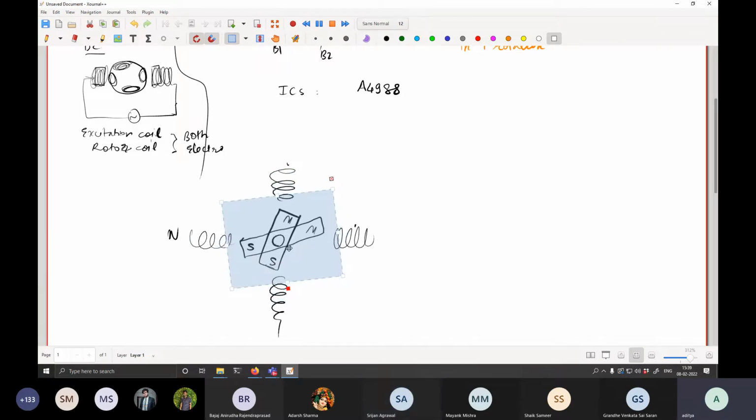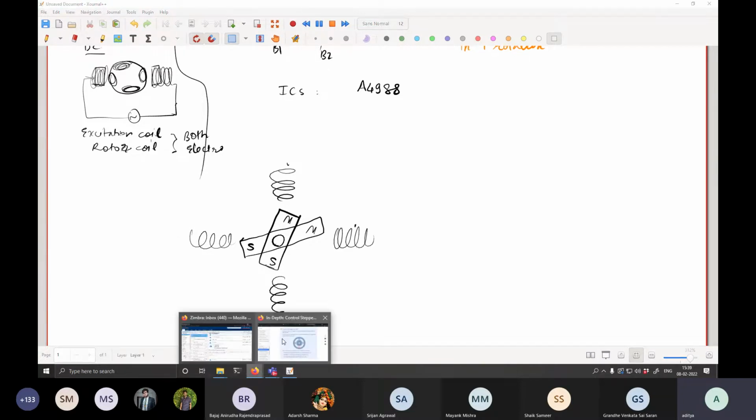Sir, I have a question. When we are stopping this motor, suppose a case occurs that the magnet aligns with the coil, and then we are applying the magnetic field again when we are starting the motor, so then it won't rotate. It will rotate because of the fact that the two rotor cups are offset. That is why that offset has to be there. Otherwise, it will just stay in place. It will never rotate again.